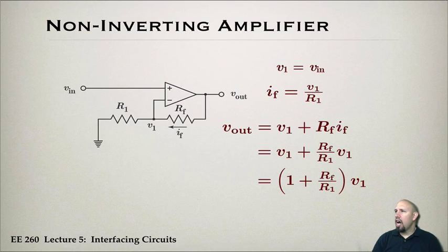We can also get a non-inverting amplifier. So here's a configuration for a non-inverting amplifier. Notice that we have, again, a feedback resistor here. Notice that the feedback always goes through the negative terminal. And again, when you take a look at systems, you'll see why that's the case.